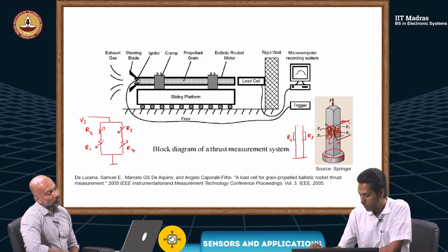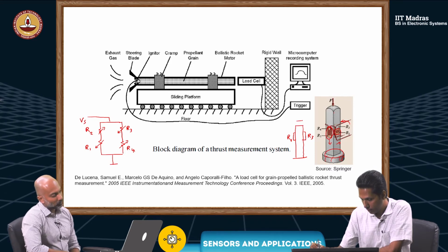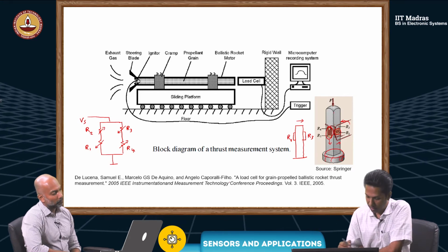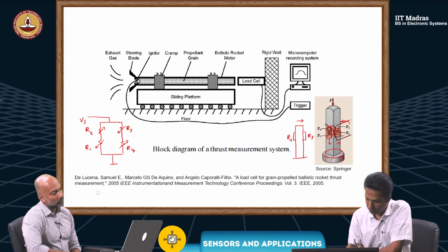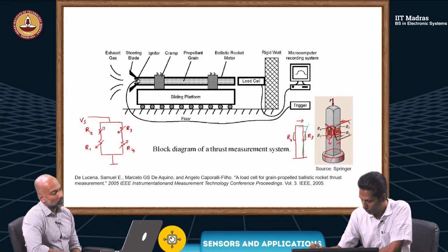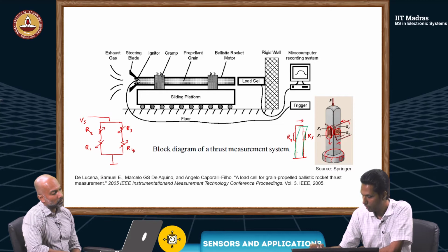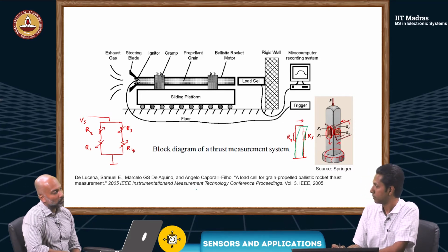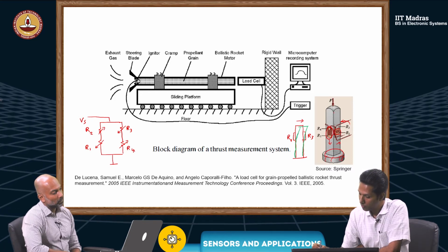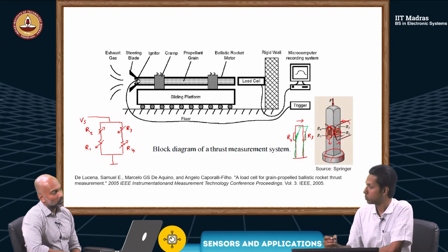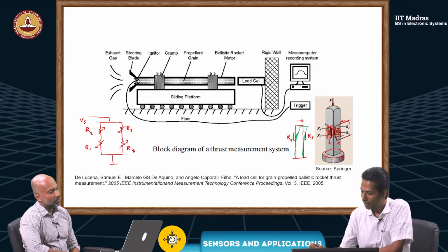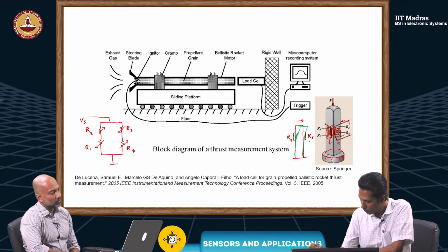Now, what I am saying is, suppose there is a component of force in this direction. In that case, I will use a different color. Of course, it's an exaggerated drawing. Let's say it gets bent this much. Now if you look here, due to the bend, this area is going to get elongated, correct? And R3 will reduce further.